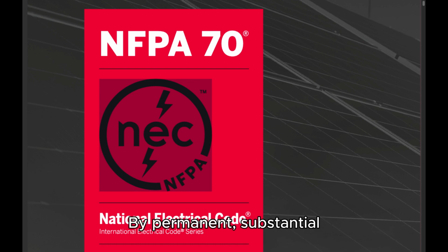2. By permanent, substantial partitions or screens arranged so that only qualified persons have access to the space within reach of the live parts. Any openings in such partitions or screens shall be sized and located so that persons are not likely to come into accidental contact with the live parts or to bring conducting objects into contact with them. 3. By location on a balcony, gallery, or platform elevated and arranged so as to exclude unqualified persons.